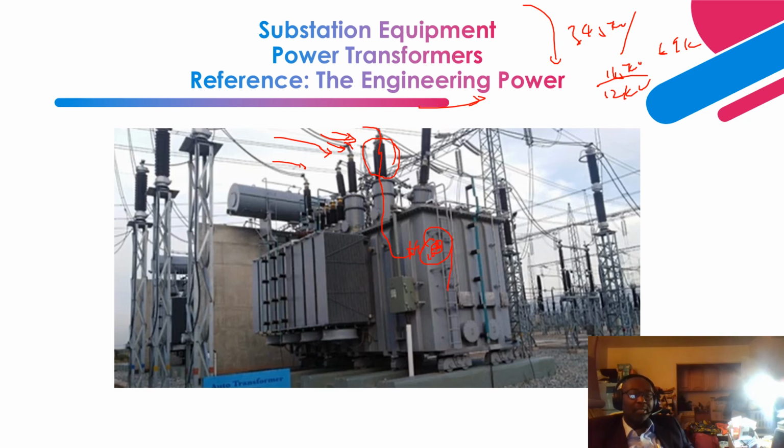So this one is just a single link, phase A. Then a similar one for phase B, phase C. So this is what is inside this transformer. This is what they call the turret, right? Turret. Okay. So this is where all the bushings are located, and where all the CTs are located, right?